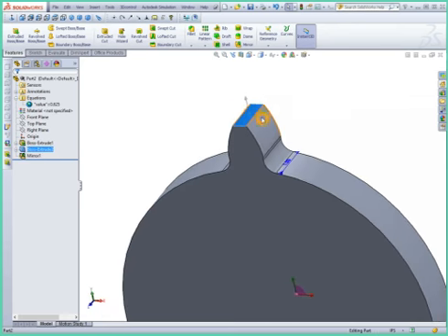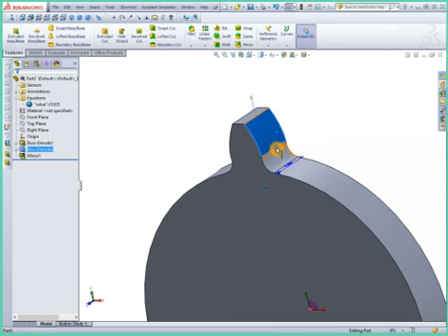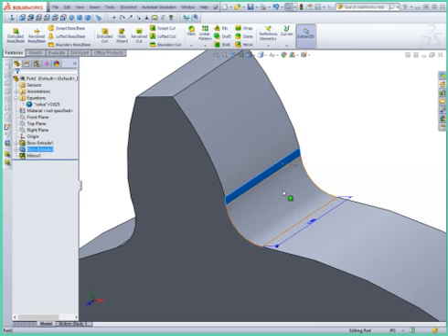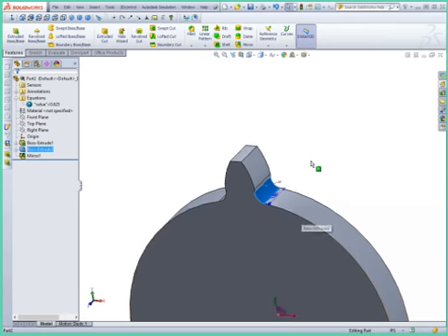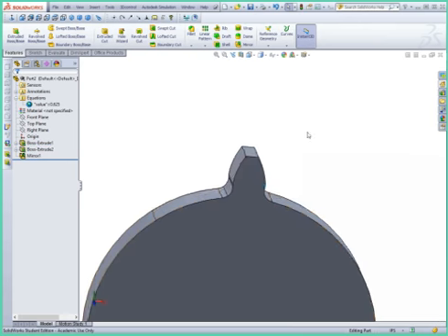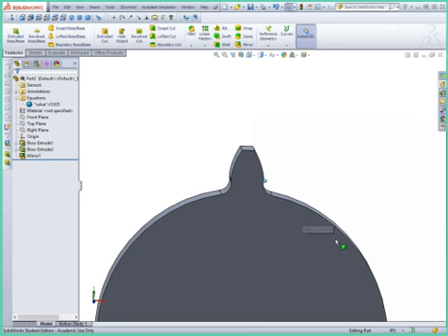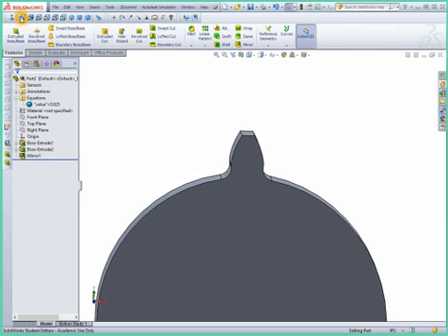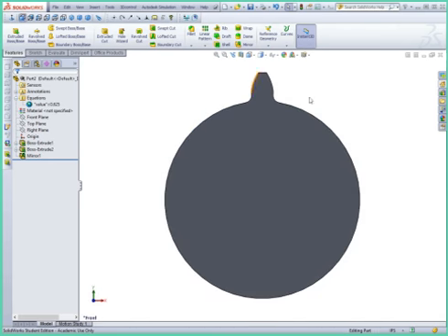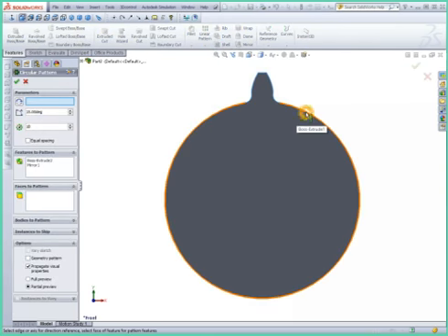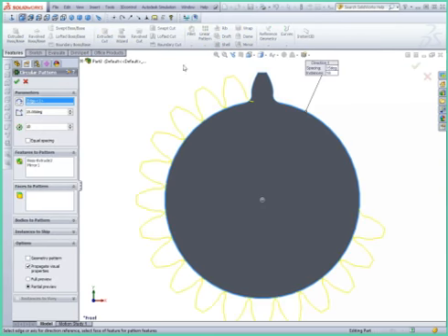So you can see the involute tooth profile, the top face of the gear, our flat end there, our radius, and so that's an entire tooth profile. The next step is just going to be to circular pattern that. So we can pick our boss extrude, our mirror, and do a circular pattern. Click on the circle that we want to revolve that around, and it's just a matter of picking the right values.